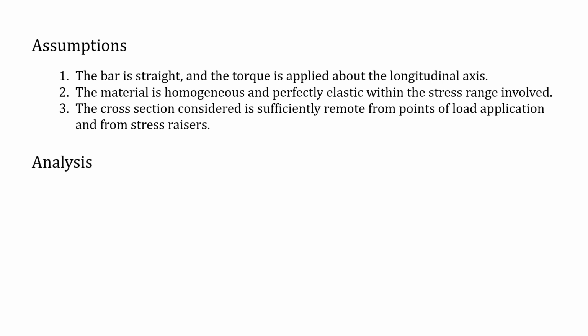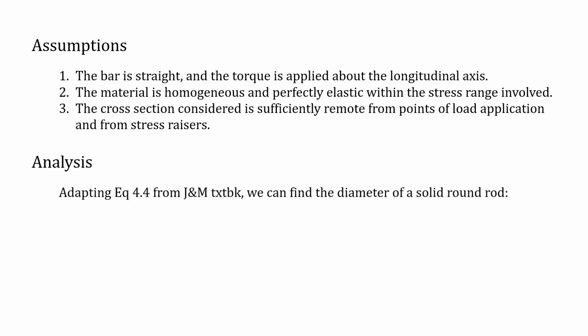Now moving on to actually solving the problem, so we're getting into the analysis. If you adapt equation 4.4 from the textbook, we can find the diameter of a solid round rod, so that's our torsion rod. So this is equation 4.4, and we can rearrange that to get an expression for the diameter, just in terms of your torque and your shear stress.